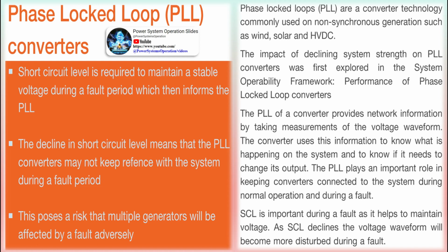An arc blast produces a shock wave that may carry vaporized or molten metal, and can be fatal to unprotected people who are close by. Fault current calculations are necessary to properly select the type, interrupting rating, and tripping characteristics of power and lighting system